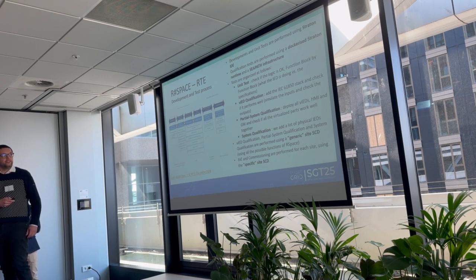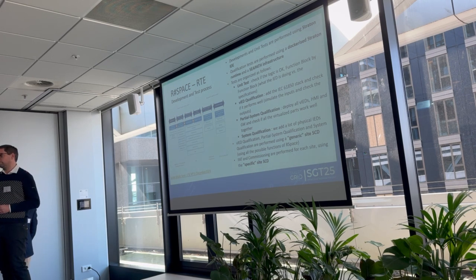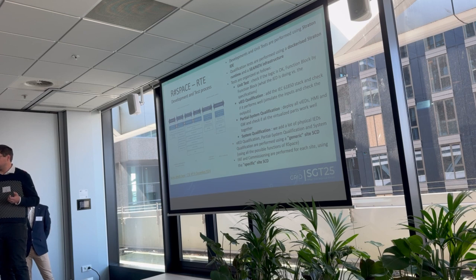So first, unit tests, easy. We check just if the logic is okay. So we check our algorithm, basically. If I have some breaker failing, I am sure that my breaker failure algorithm is functioning well. In a second step, we perform virtual IED qualification, which is to say we add the 61850 stack and we check if it performs well. So we simulate the inputs and we check if the outputs are okay. Again, this step is fully automated. We have automated test tools we developed internally at RTE.